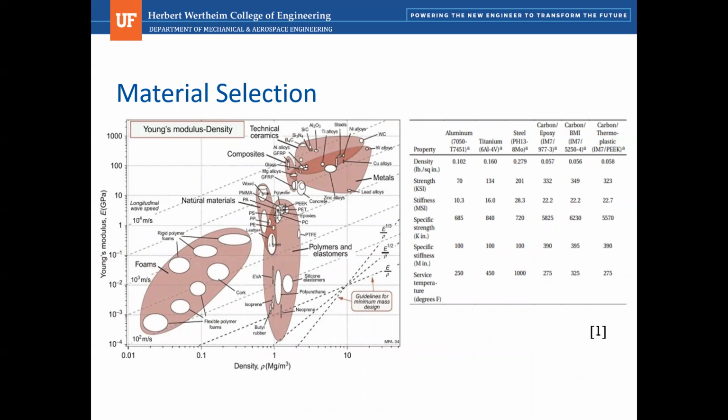When identifying viable materials for these structures, we performed a qualitative analysis on various standard aerospace materials like steel, aluminum, and titanium, primarily with respect to machinability and compromises between material strength and density. This is usually accomplished using Ashby charts like the one shown on the left. For example, using a formula for simple cantilever beam deflection, which is common in tip displacement analysis, and expressing that equation in terms of length and volume, it becomes proportional to the ratio between density and the third root of elastic modulus, which would correspond to this length on the diagram right here, or that slope.